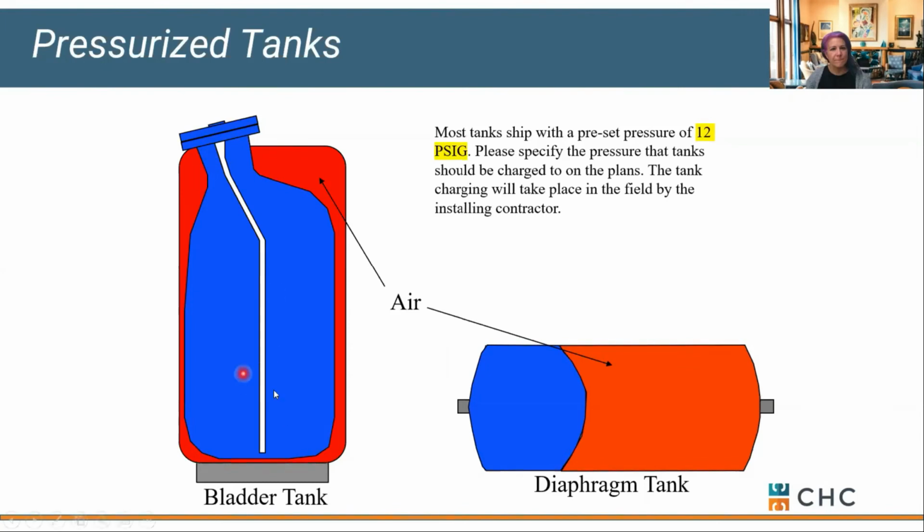But another one might be initial startup. There is a dip tube that goes into this tank. And if your air charge is set too high, you can actually impinge the bladder into this dip tube. So sometimes you have to add a little bit of water pre-charge to prevent that. But all those are kind of your key points.